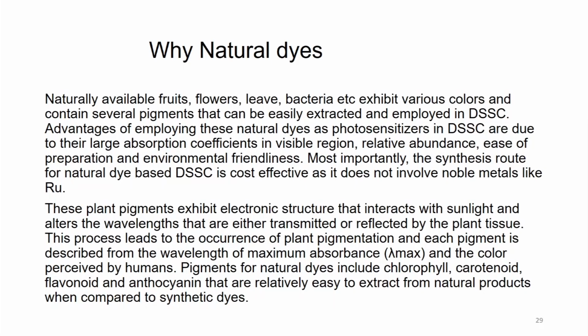Why natural dyes? Because they are available. Fruits, flowers, leaves, bacteria, etc. exhibit various colors and contain several pigments that can be easily extracted and employed in DSSC. Advantages of employing these natural dyes as photosensitizers in DSSC are their large absorption coefficient in the visible region, relative abundance, ease of preparation and environmental friendliness. Most importantly, the synthesis route of natural dye based DSSC is cost effective and it does not involve noble metals